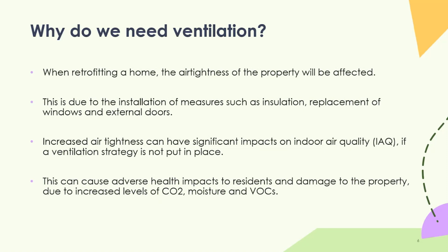If you think about circumstances where you have, in the summer, that's not a problem. You want some background ventilation. It's not going to be something that's creating a problem. But in the winter, if you have very cold weather and a strong wind, that will be sucking your warm air out of the house and introducing very cold air into the house, and that's going to be wasting a lot of energy in terms of the heat loss.